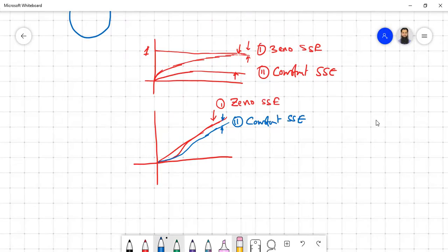The third one is where we always maintain a different slope, so the distance is always increasing. One is going that way, the other is going another way, so the distance keeps increasing. At steady state, the error will actually be infinite. This is the physical significance: the output will never be able to follow the input signal from the point of view of the steady state error.